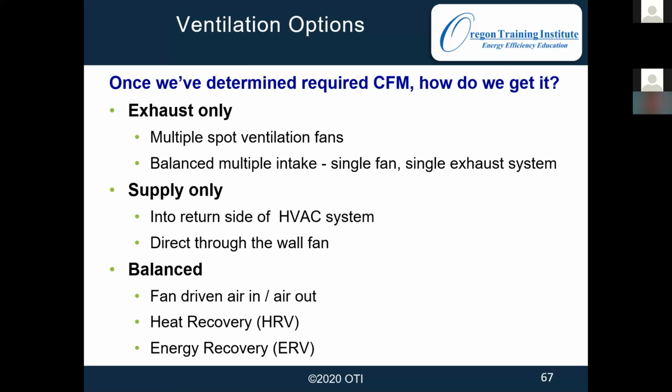It's the same amount of air being sucked out of the house as is getting blown in. And then we're also capturing the heat with the heat recovery, or the heat and the humidity in an energy recovery ventilator. So some different styles, of course, exhaust only being the most common.